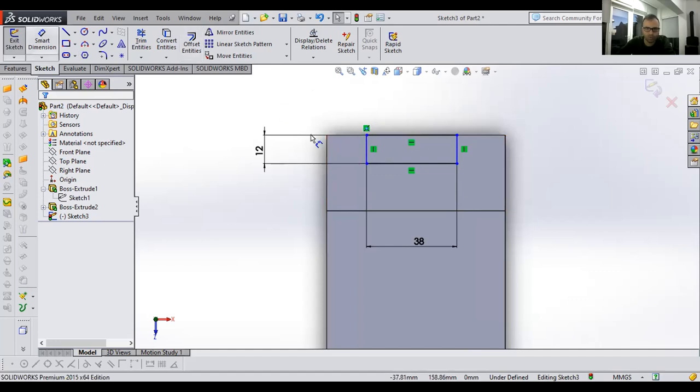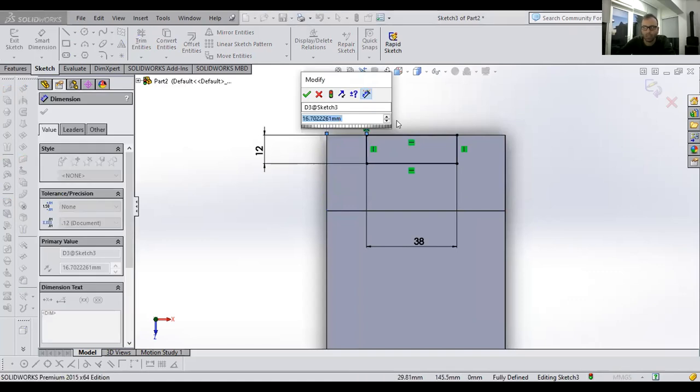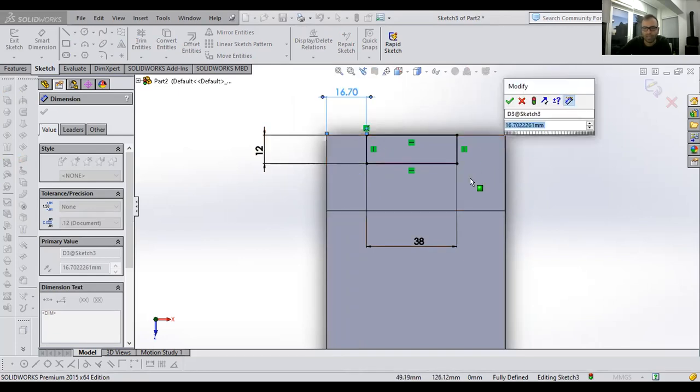That's why I'm going to say the distance between here and here is, when you check the paper, this distance is not given on the paper. But when you're looking at the part, if this distance were required, it should be given on the paper. But it is not given. It means that you have to put this rectangle at the center of this line. This line is totally 75 millimeters, if you remember.